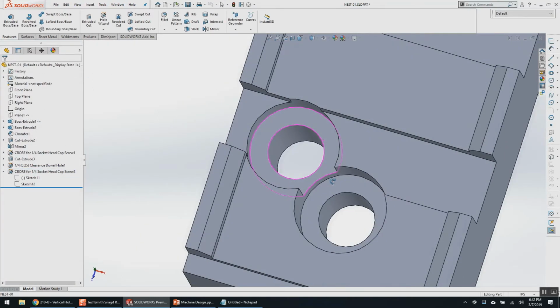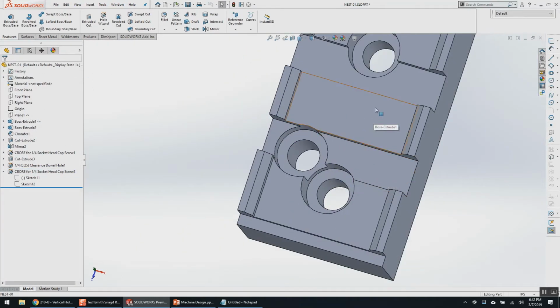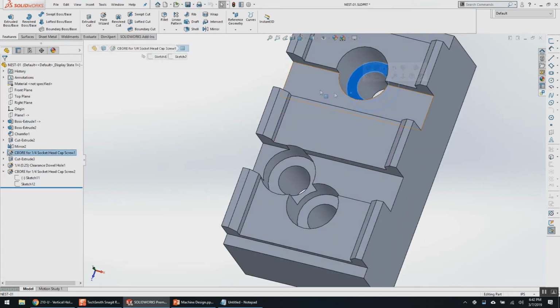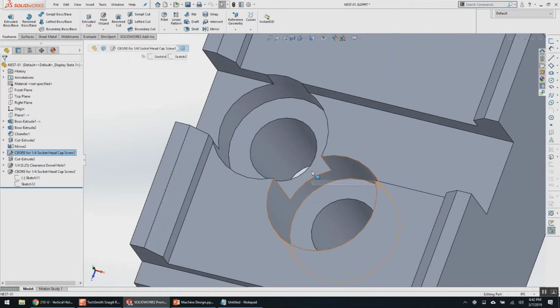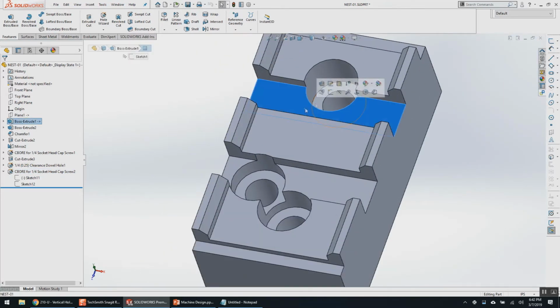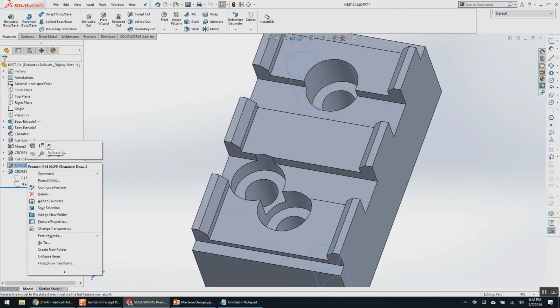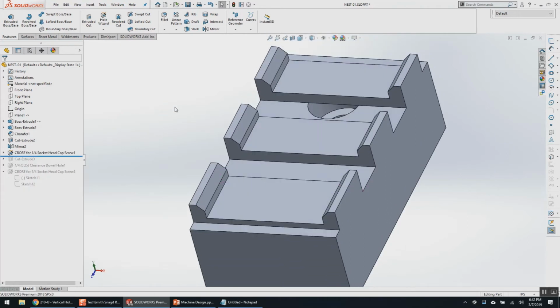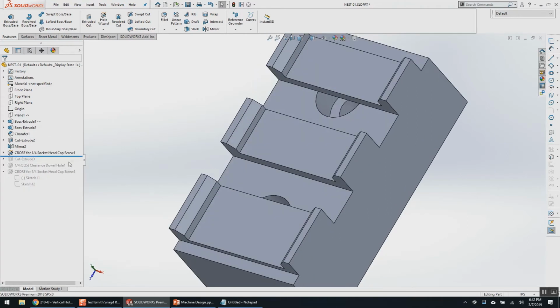So generally, as you saw me go through the decision-making process of the design, in this instance, I would probably pick the lowest surface that I have to clear, right? Because the distance from here to here is only 1.5 and we need 2.5. So I'm 100 thousandths short. So generally, I would pick the low surface, bury it, and then you get a result that looks like this, which to me is acceptable from a design iterative process standpoint. And then do a dumb cut extrude that's through all the other way, because a through all cut extrude will always make up the distance. As long as my counterbore starts on the lowest surface, I'm never going to have head clearance issues, and the design will, quote, always work.